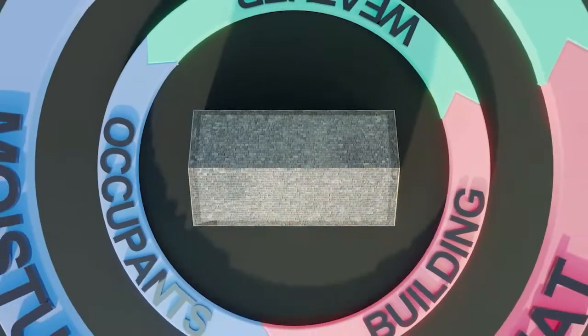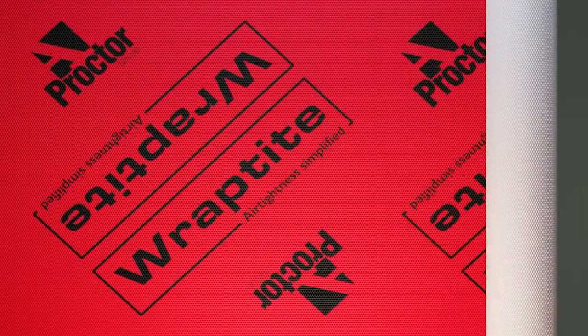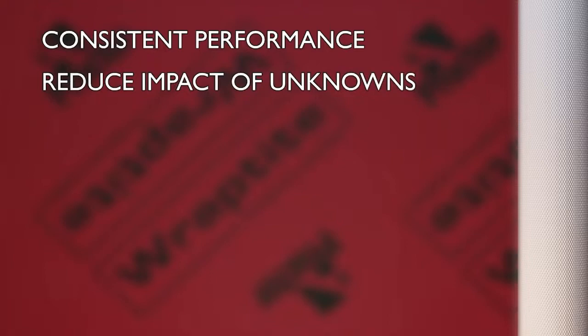These factors feed into developing an understanding of the management of the heat, air and moisture in the structure, and this holistic approach is fundamental to a successful retrofit strategy. Failure to consider the impact of each measure across the entire project can cause a range of problems, from internal wall insulation leading to hidden mould, through to poor air tightness reducing the effectiveness of heat pumps. Construction membranes have an important role to play in managing heat, air and moisture by increasing the level of control we have over these factors, especially if there is a degree of ambiguity over the existing fabric composition and performance.